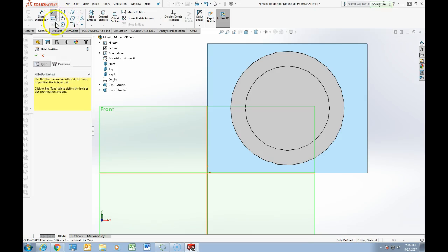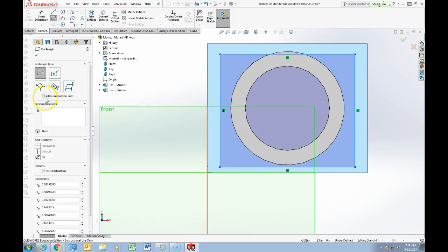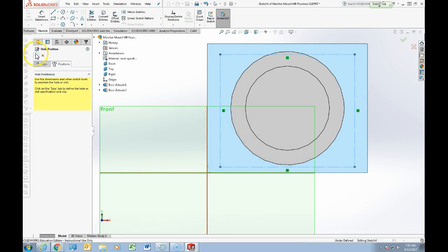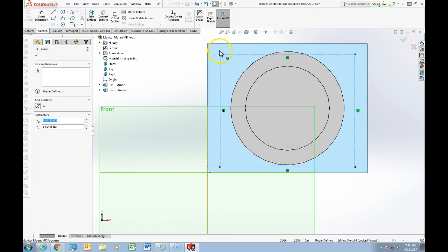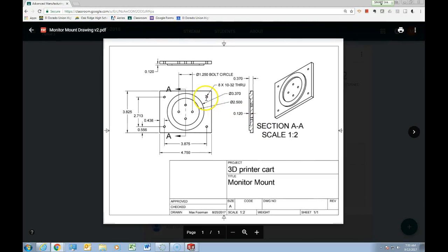And actually in this case what I could do is a rectangular feature. So there's a rectangle, and that's as if it was an actual full rectangle. So I'm going to click on for construction. So guess what? We can make a rectangle that's a construction thing too here, right? And the other thing that's implied is, again, these are symmetric. The circular features that are here, or the hole features, are implied to be symmetric around the center of the part.